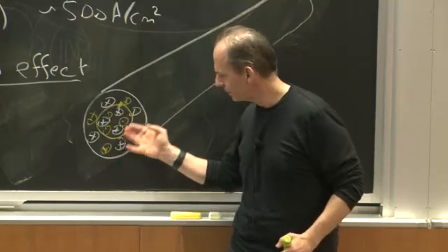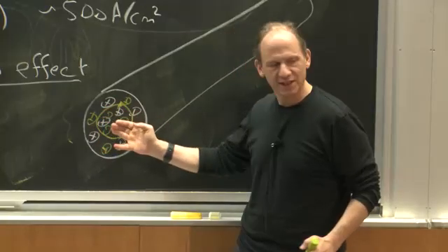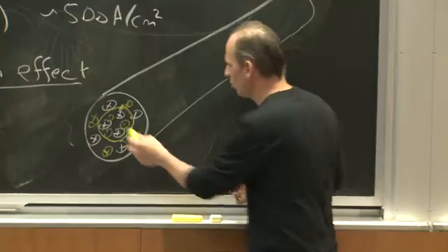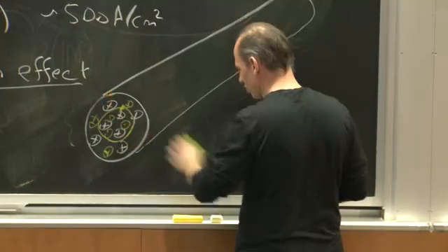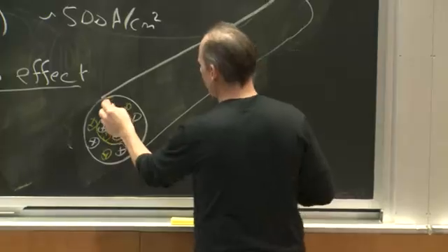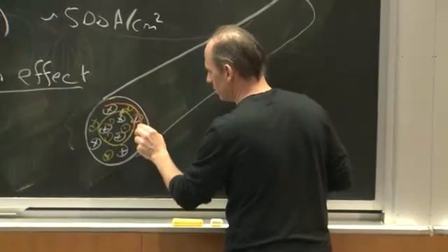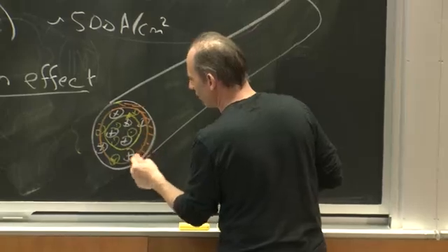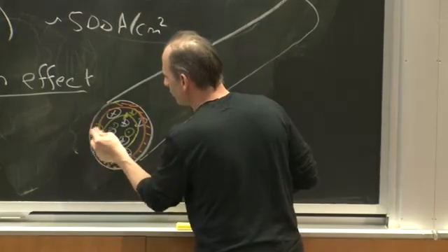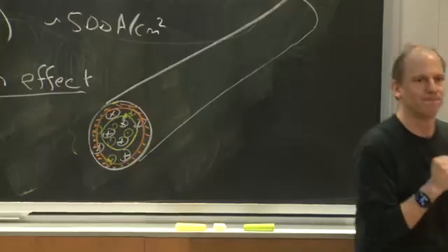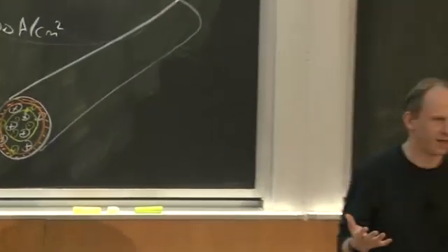If you go to a high enough frequency, the net current will be carried only in a band around the surface of the wire. So instead of getting the full wire cross-section at high frequency, you will only get to use the surface of the wire. That's what's known as skin effect.